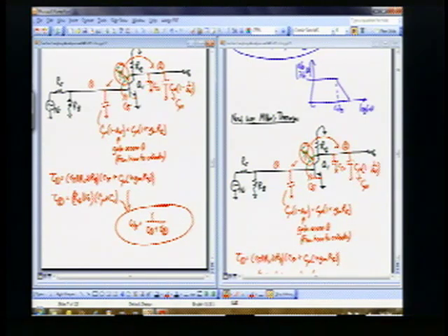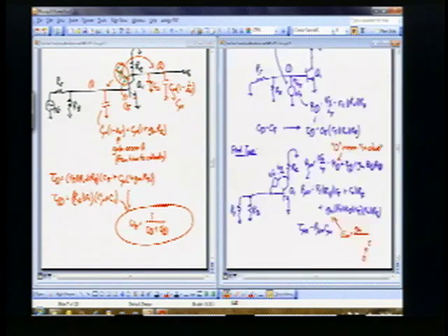So if you compare the two solutions, this was the driving point resistance for the C mu capacitance. It multiplied RS times RB times R pi times C mu. You could see RS parallel RB parallel R pi, that's multiplied by this C mu, because of the 1 times C mu. That's also multiplied by GM times C mu, which you see right here, GM times that C mu times that, but also times the output resistance, which you also see right there. Okay, so the two give identical solutions.